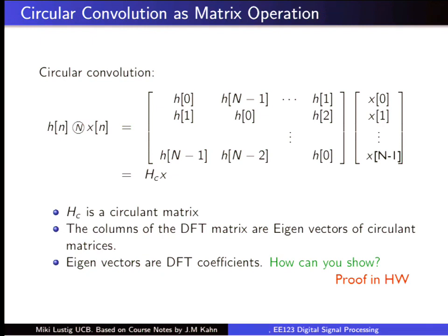And if I want to compute that circular convolution at a particular point, I need to place that filter at a particular offset such that they fit. And then if I want to move it by one sample, the next row will be just shifted by one sample, circularly, and so on and so forth. So this is effectively what you're getting here. Circular convolution will exactly correspond to putting your filter in as a vector and then circularly shifting it. Hence, circulant matrices. So that operation could be described by a circulant matrix, which is great.